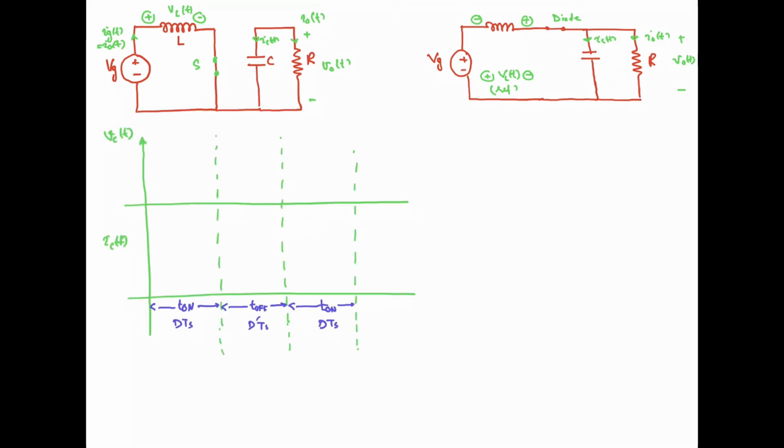So in the first mode of operation, we just look at this part. The capacitor current is in the downward direction, that is the reference polarity, but it is going to provide the current to the load, and if the load polarity is plus minus, then it should be in this direction, from the top to bottom in the load. So it means that the slope of the capacitive current with respect to our reference will be the -1. So the capacitor current will be the -1 with respect to this one.